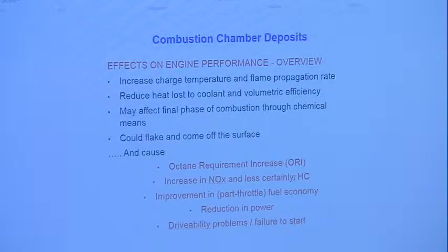In some experiments, hydrocarbon emissions go up. In some experiments, they come down. In some, nothing happens. There is a lot of experimental data like this. This is because there are multiple mechanisms. They can absorb fuel. Because of high temperature, the oxidation of hydrocarbons can go up. So there are all these competing effects, and depending on how you run the engine, what the engine design is, you might get different results. But NOx always increases, and this is the most interesting part, actually.